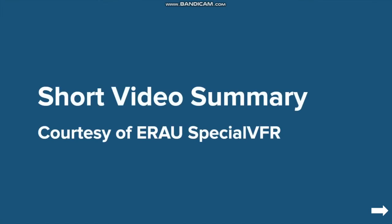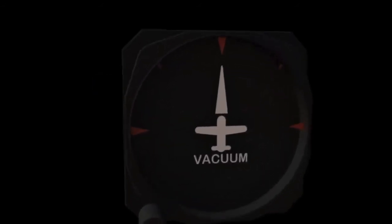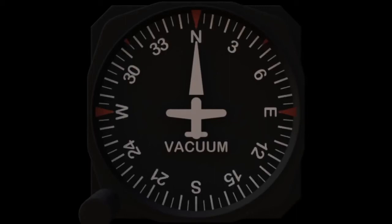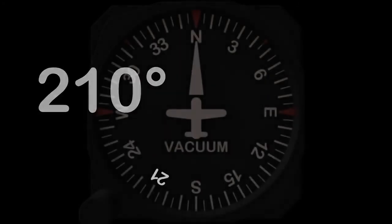Next up, we'll be showcasing a short video summary courtesy of ERAU Special VFR. The heading indicator senses the airplane's movements and displays heading based on 360-degree azimuth in 5-degree increments. The tick marks are labeled every 30 degrees with the final 0 omitted. For example, the number 6 indicates a heading of 60 degrees while 21 indicates a heading of 210 degrees.